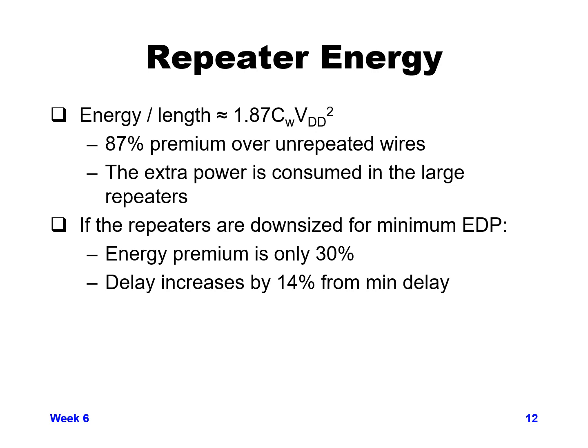So one final thing to note about repeaters is the previous discussion was how to minimize the delay getting from a driver to a receiver that's a long distance away. Putting in repeaters will improve your delay for long distances, but it will also increase your total amount of power consumed, because each repeater will add some additional gate size and additional energy required.